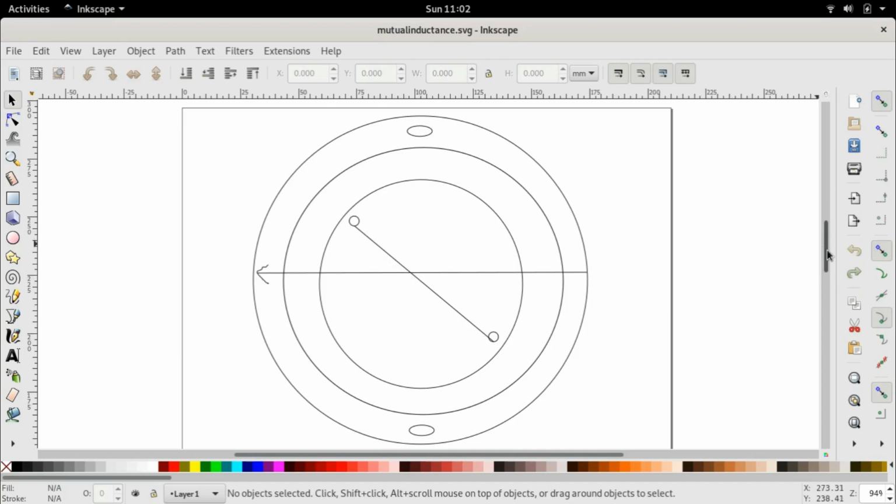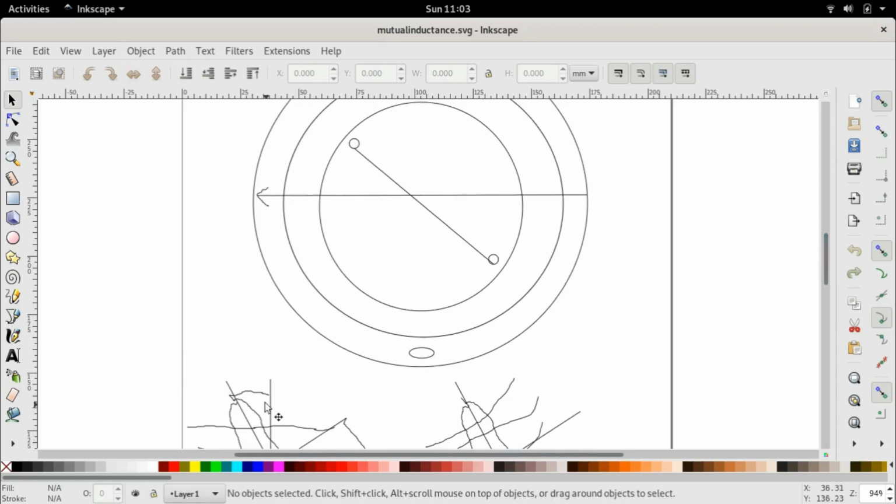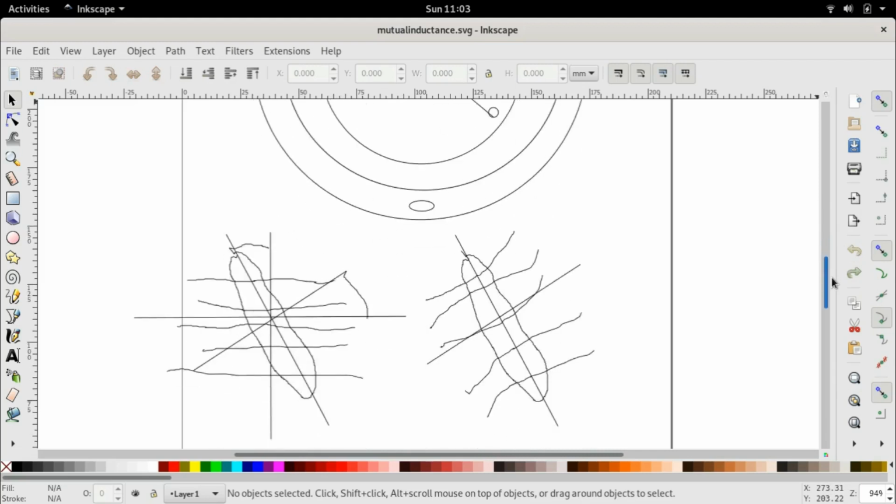And we had used some of these diagrams to show that as the rotor rotates, the mutual inductance between the stator and the rotor will be a cosine of this rotor position angle, which can be said to be the angle between the axis of the stator and the axis of the rotor, or could be the angle between the stator flux and the rotor flux. The reason is because the stator flux and the rotor flux will always be perpendicular to the axis of the stator and the rotor respectively.